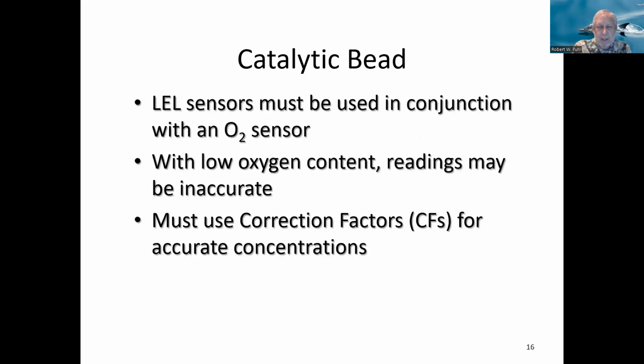LEL sensors must be used in conjunction with an O2 sensor. With low oxygen content, readings may be inaccurate. Must use correction factors for accurate concentrations.